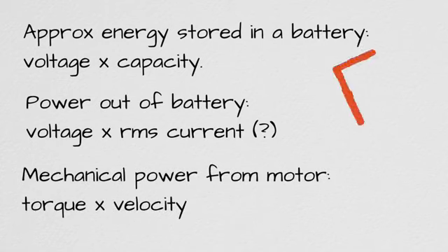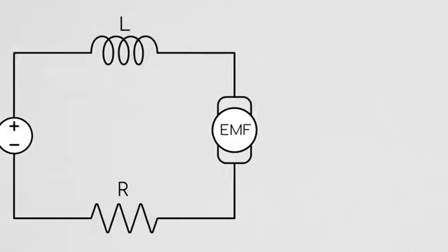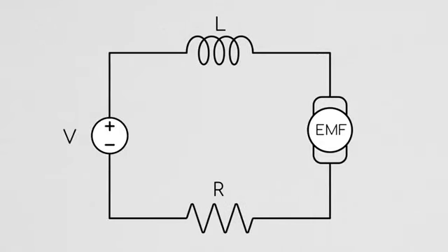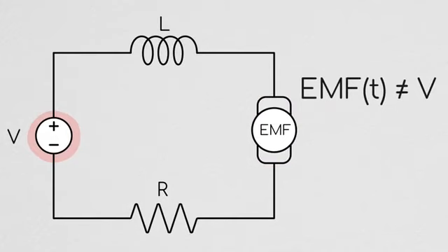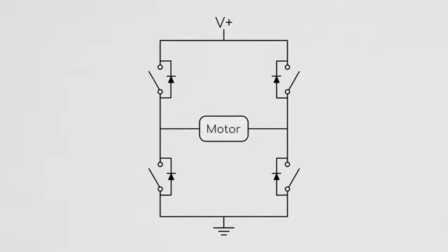So there's a couple of different ways to explain why the methods of calculation I was using there were incorrect. The quickest explanation of this is that, as I mentioned a few episodes ago, the voltage across the motor that is converted to mechanical energy is the back EMF, not the supply voltage. Because of this, it would be incorrect to multiply the motor current by the battery voltage and call that the power input. The other explanation, which personally helped me to understand this all more intuitively, is to look at the source of the current running through the motor.